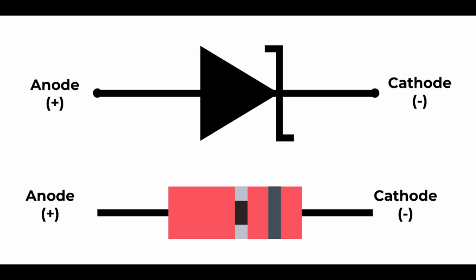Op-amp level shifter. Operational amplifiers, op-amps, can be used to shift the voltage level of a signal. A simple op-amp level shifter can be constructed using an inverting or non-inverting amplifier configuration, which amplifies the input signal to the desired output voltage level. Level translation ICs, specialized level translation integrated circuits, are available that can shift signals between different voltage levels with minimal additional components. These ICs are designed to handle bidirectional signal shifting and are commonly used in mixed voltage systems.